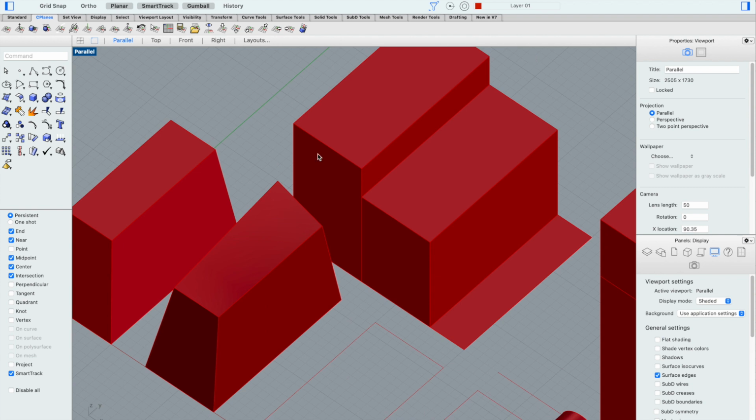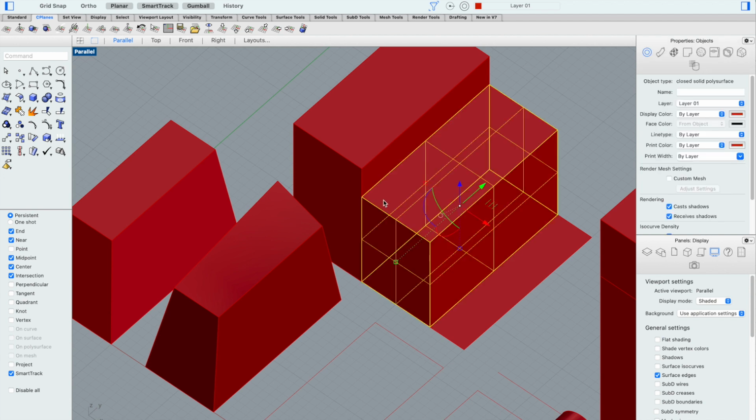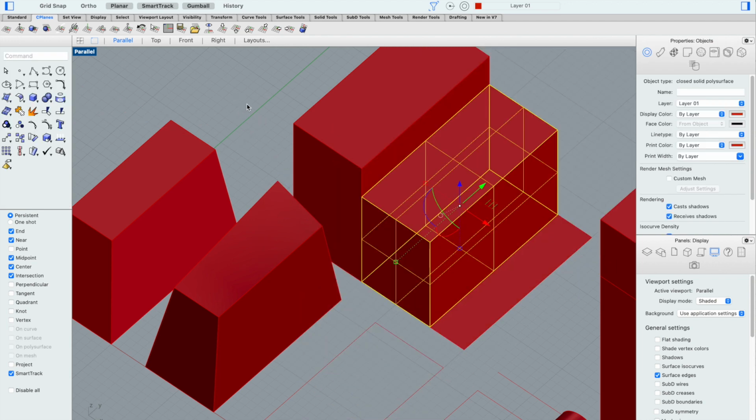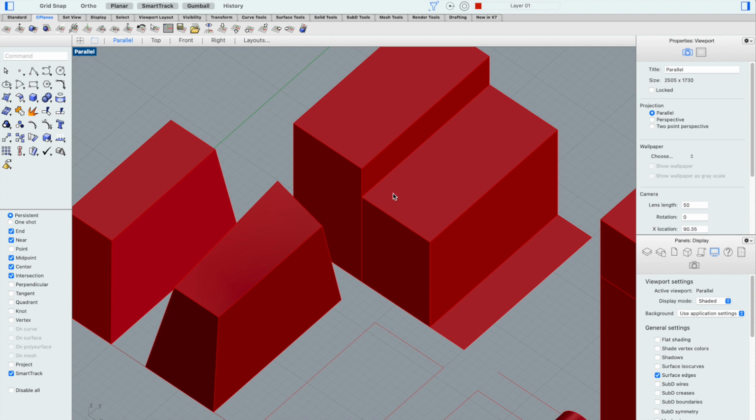And just like in 2D, the 3D resizing commands work very similarly. So if I use scale, I can change the scale of any of these objects. Scale automatically will scale it in 3 directions. If I just hit enter, it will scale it about a centroid. And if I want to make this box twice as big, I can just say 2. Now it's twice as big. Done. But if I want to be smarter about it, then I'm going to use scale in a different way.